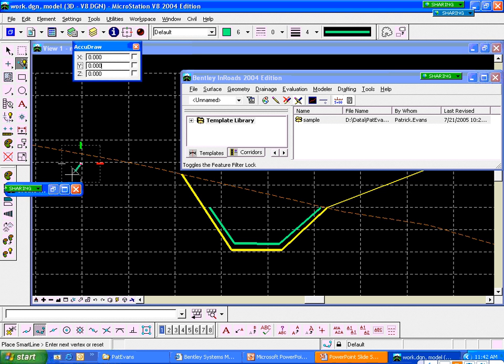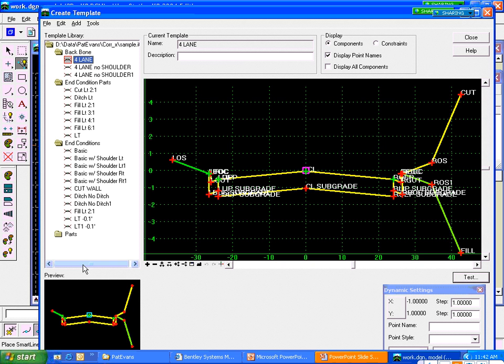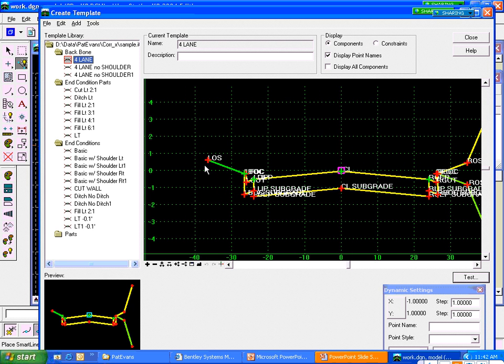And so let's go back to this and let's talk about it. We have two targets. Same target, both ones. And we're going to kind of use pieces, which may or may not be something you're familiar with. So let's go over here. I'm going to come over here to this 4-lane section right here that I've got. And I'm going to switch over here to the left side for this testing. And I want to add a 2-to-1 slope going down, and then we'll check for the ditch.